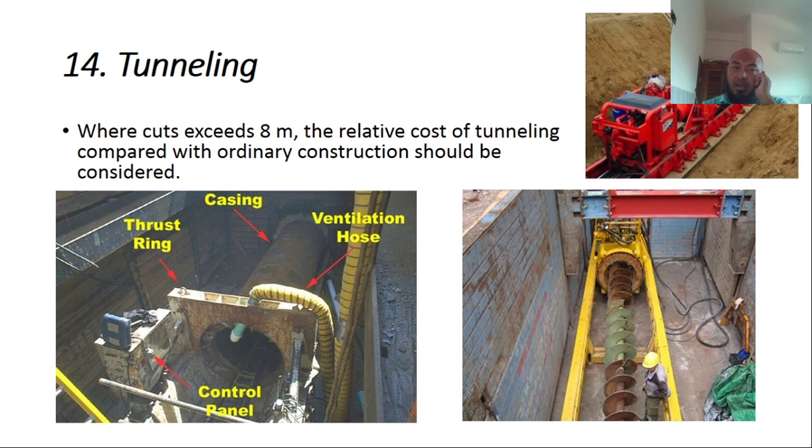And then we have tunneling. Where cut exceeds 8 meters, the relative cost of tunneling compared with other construction should be considered. So you can see, we can use this one.